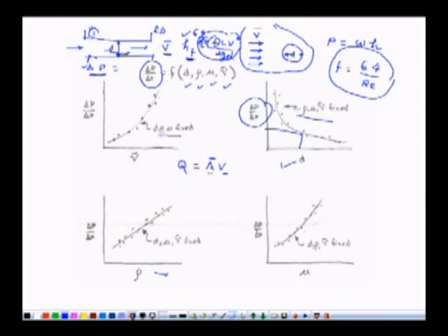And then we can answer that for this density, suppose we want to know what is the del P over del X, then corresponding to this point, draw a horizontal line and find out the corresponding del P over del X, keeping other variables fixed, like diameter, viscosity and velocity